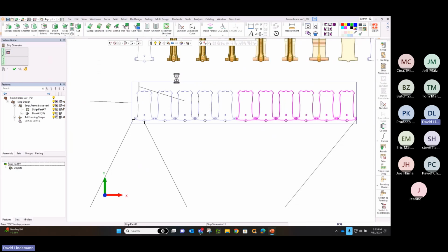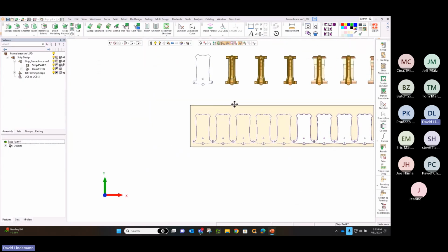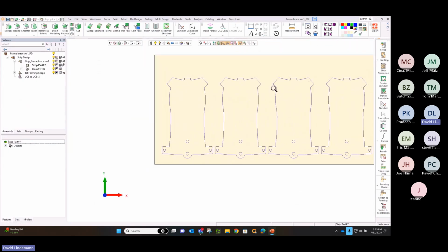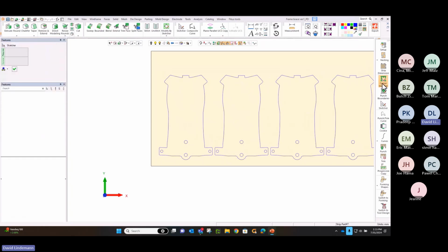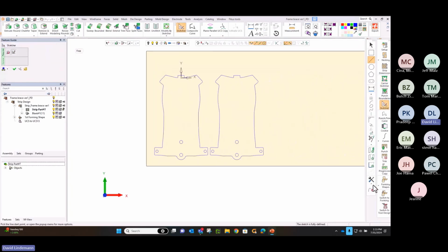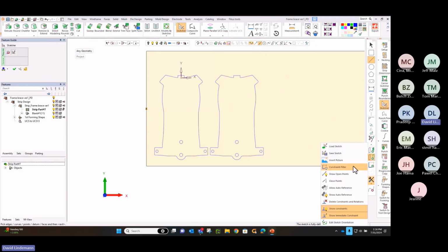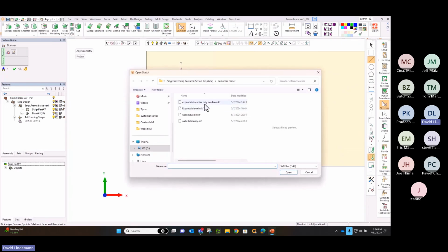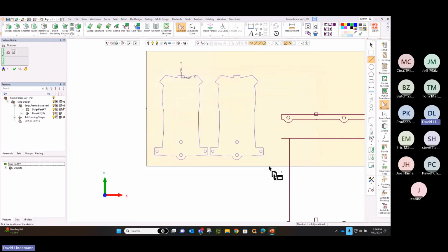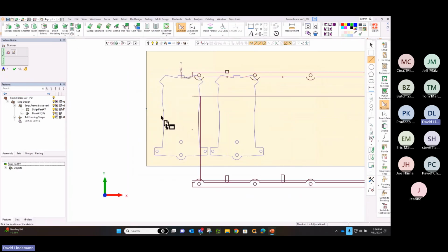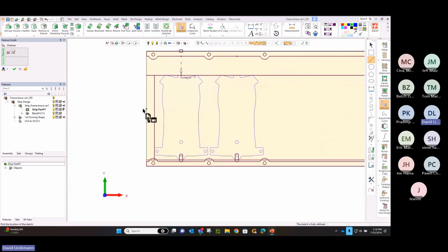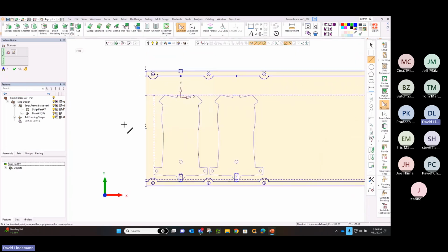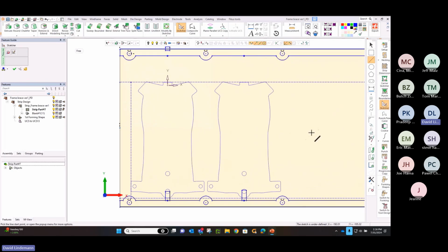So here I'm thinking maybe a carrier on the top and bottom, and I'm going to leave the top with more room because I need to put an expanded web in there. Here I can sketch out what I want for this particular carrier to look like, or I can do what I'm doing here, which is have a saved preset catalog of different types of carriers. That way I'm not always sketching it out. Just put it in. I can alter the dimensions as I need to accommodate what that progression really is.